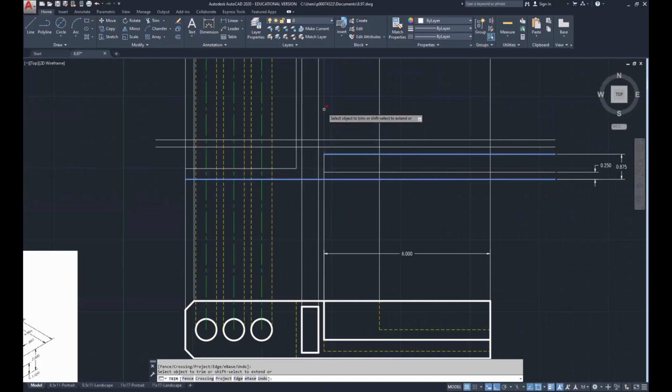And then above and below. Right click, enter. We can also now get rid of these extra lines here because we've worked with those. Right click, repeat trim. Selecting our baseline. Right click, we'll take out this line, and this line. Right click, enter. And then remove those dimensions.